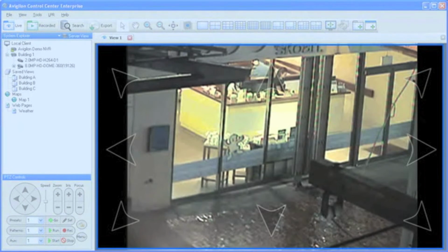When controlling a mechanical PTZ, the same mouse controls as digital PTZ will also control the optical zoom as well as the mechanical panning of the camera. When scrolling the mouse wheel up with a mechanical PTZ, it will control the optical zoom to zoom in. When scrolling the mouse wheel down with a mechanical PTZ, it will optically zoom out.